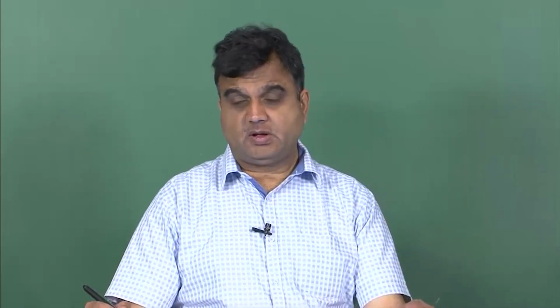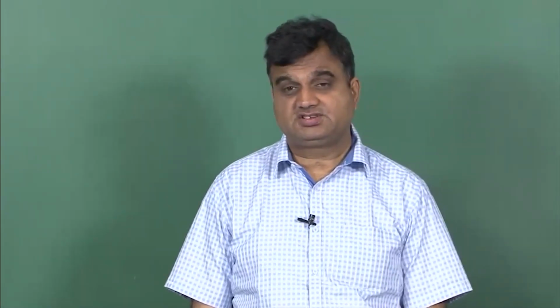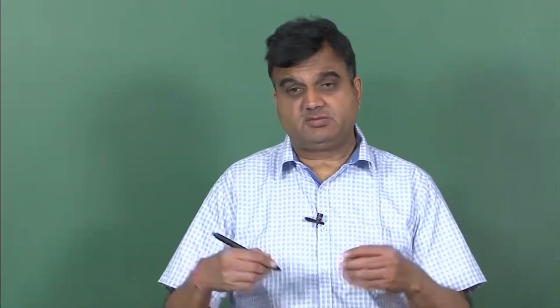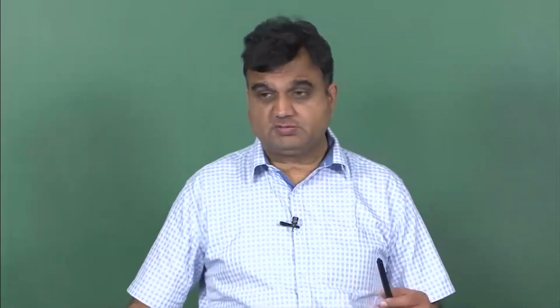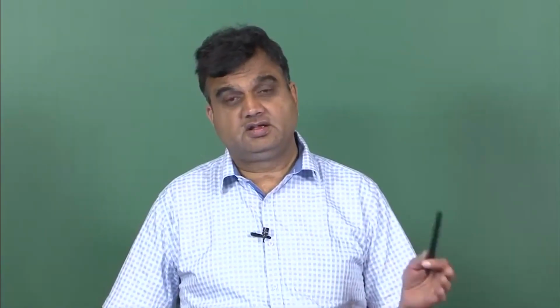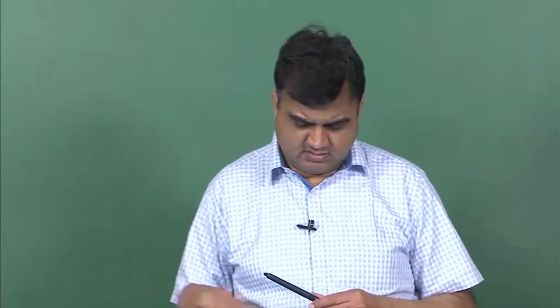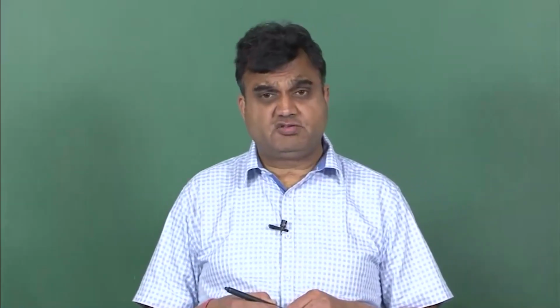So, first in terms of engineering constants we calculate the Q matrix and the S matrix, and from those we can calculate Q bar and S bar matrices, and once we have those matrices in place, then we can relate strains and stresses in the way we want. So, this is the conclusion of today's lecture.